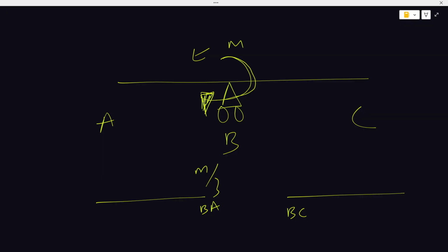Let me recap. When we are dealing with distribution, we're dealing with distribution from joints to member ends. Do you get? So when I say distribution moment, there must be a distribution factor to distribute the applied moment at the joint. This distribution factor would come from the stiffness of the member portions.